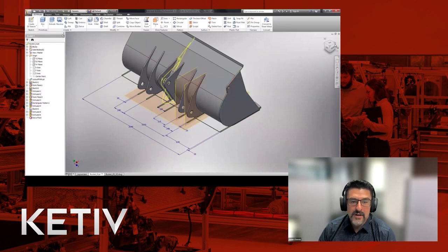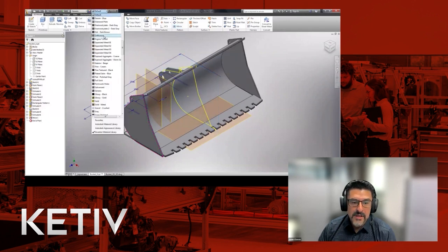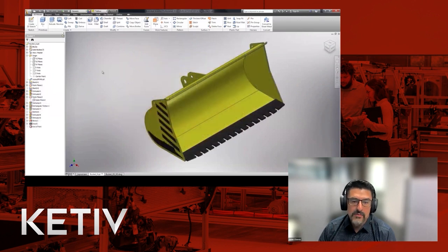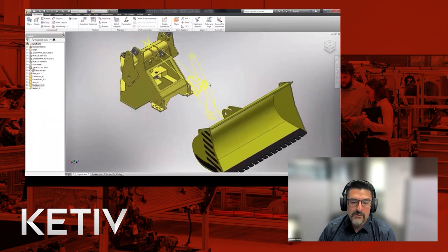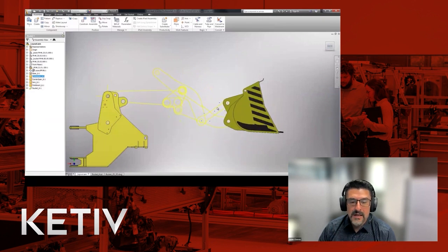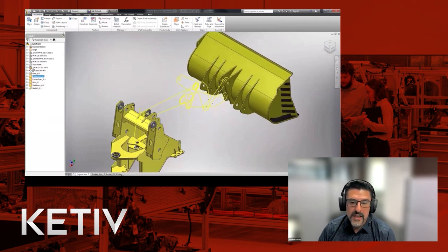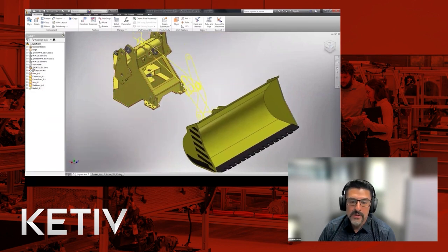So in a single part, you could turn these on and off. And like I said, there's a workflow where you can explode this and turn each body, each one of these extrusions, into its own individual part and an assembly that contains them all. So now what's left again is adding the information that you normally don't have in 2D: colors, decals, part numbers, even material properties. Is this made out of steel? So once you have this, you can see we've got to this fairly quickly. The unedited video of somebody doing this took about 12 minutes. So it doesn't take that long to copy this data into sketches, into an environment where it can be reused right away.